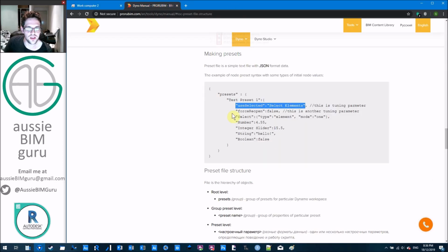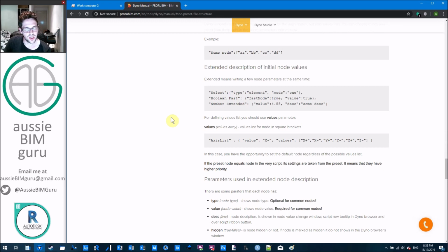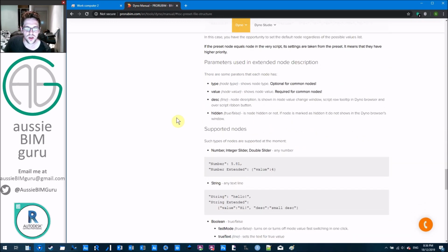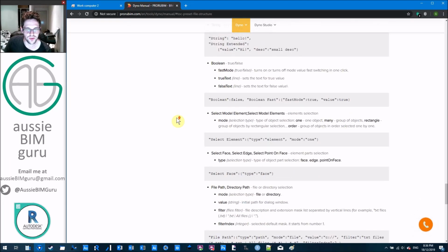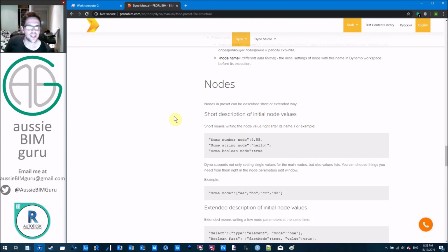The syntax for that, I believe, is on the website, or it's in their video demos. They have videos on their website as well where they show how some of these things work, so I don't want to focus on them too much. But essentially you can have more than one preset in the way your script runs. So you could say active selection or only all the walls. You could have different things that you can define within Dynamo by defining some presets, which is pretty impressive.